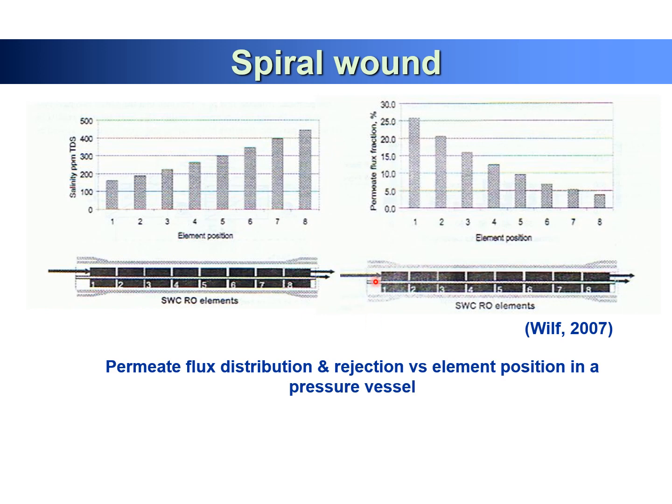Also, if you look at the permeate flux, there is relatively low osmotic pressure and then high osmotic pressure, which means you have a higher flux at the first element. You can see 25% of the water flux can be achieved at element 1, element 2 20%, element 3 15%, and then you have a high concentration of seawater and you get a very low fraction of permeate flux. At element 8, less than 5% of the water flux is coming out. So we have to calculate all the details from each element in one pressure vessel when you do your seawater design.